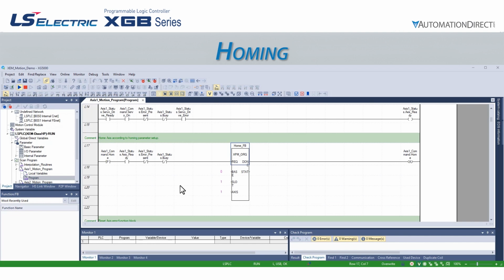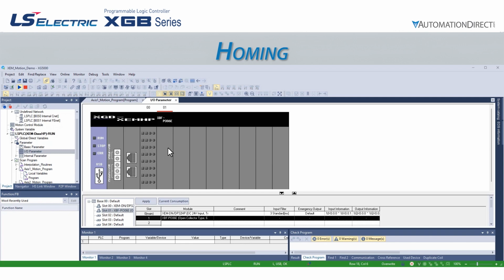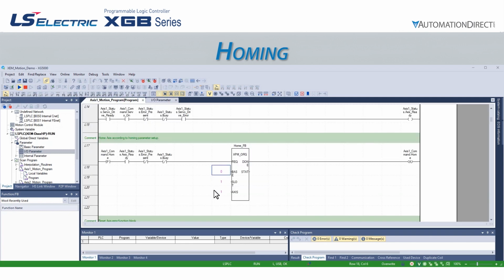The function block itself is very straightforward. We will tell it which of the axes in the controller we are commanding by listing the base, slot, and axis number. It is our main PLC, so it is base 0, and if we look in the I/O parameters screen, we see that the motion controller is in slot 1, and we are homing axis 1. In our project, we are making this function block true whenever the home command is true, and the axis is ready, and there are no errors present, and the axis is not busy.